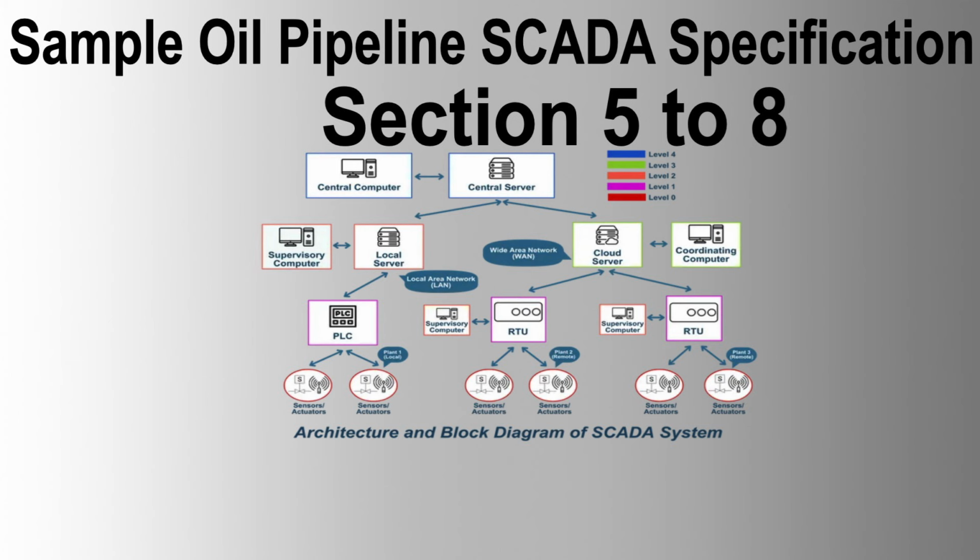Section 6. Field Marshalling Cabinets. 6.1 General. The seller shall supply all necessary field marshalling cubicles, internal wiring, and equipment for the SCADA system. Cabinets shall provide the facility for terminating all field multicore cables, including spare cores, and interconnection and cross-wiring of these cables between incoming terminals or barriers.